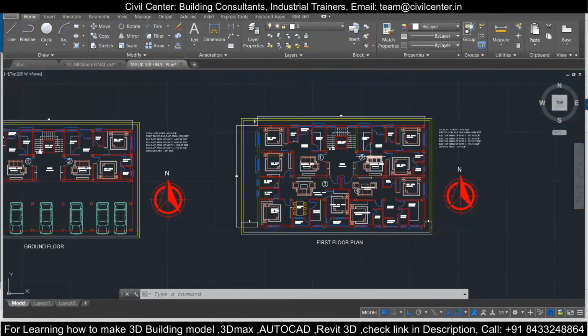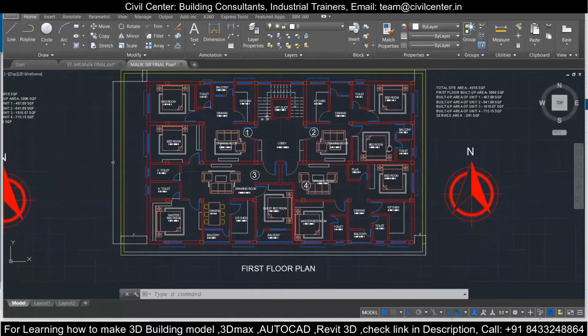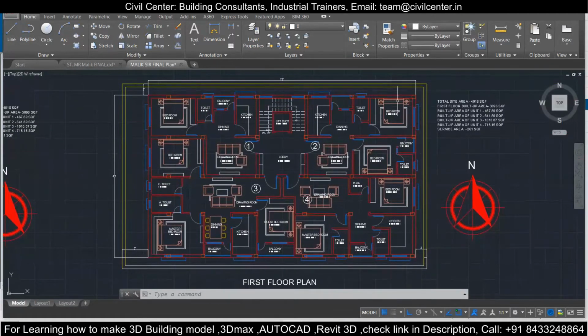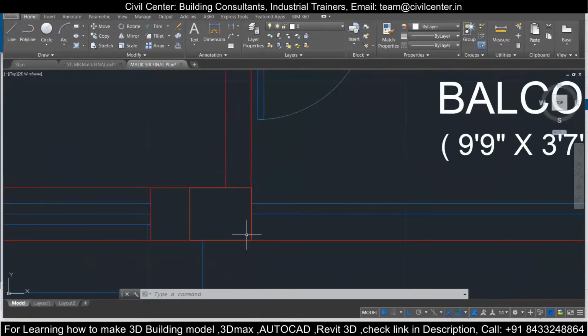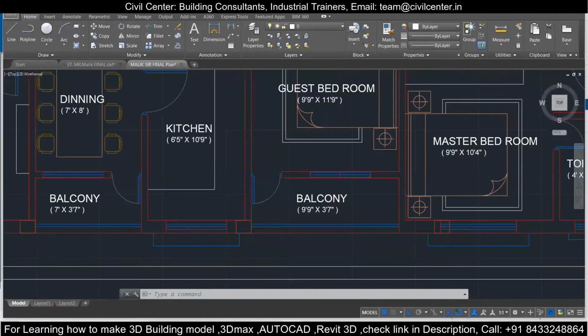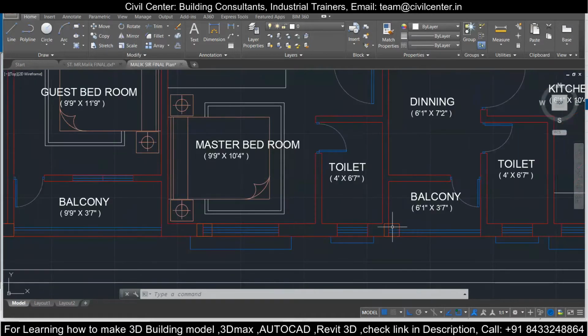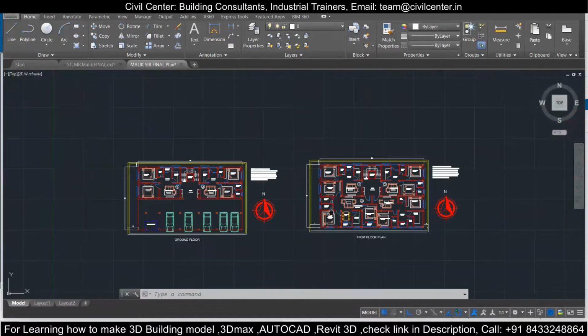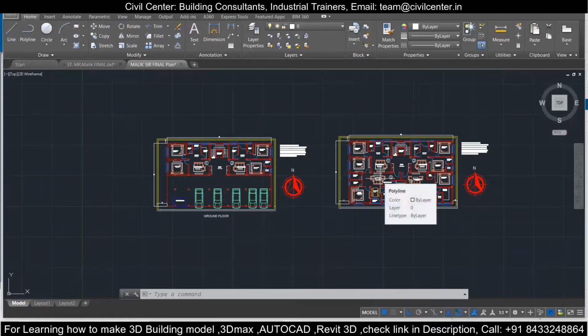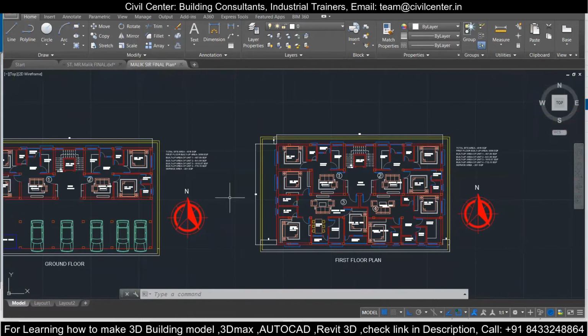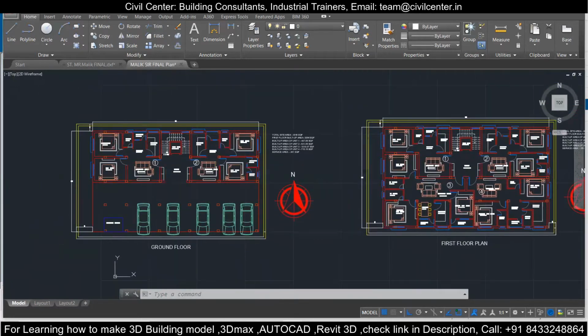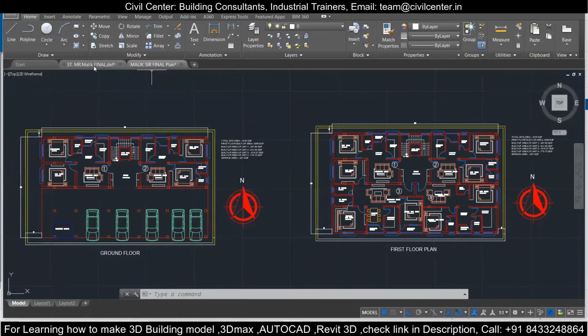Now we will go for the structural drawing after the completion of this first floor plan. You can see we have the first floor plan like this, and our columns are positioned at these places. You can see this is being highlighted when I go over here. So we have the columns at these places, and now we can analyze the structural drawing. Whenever you are working on any project in Tekla Structures, for the detailing work you will have to get your architectural plan and the structural drawing ready first.